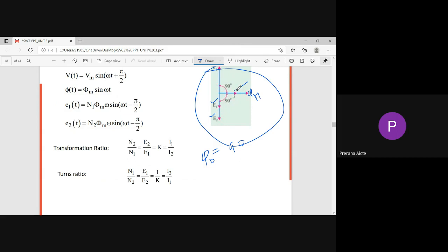When we give V1 voltage to the primary winding, the Iμ current starts flowing through the primary winding. Because of this primary current, the primary flux, the main field flux, will be set up. For that reason, Iμ, that is the excitation current, lags V by 90 degrees.